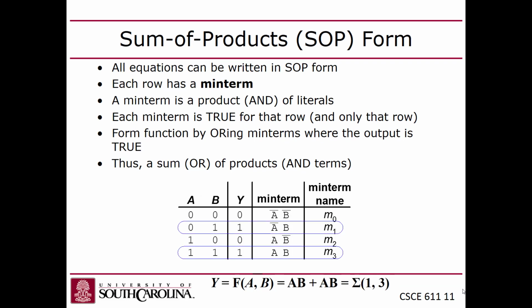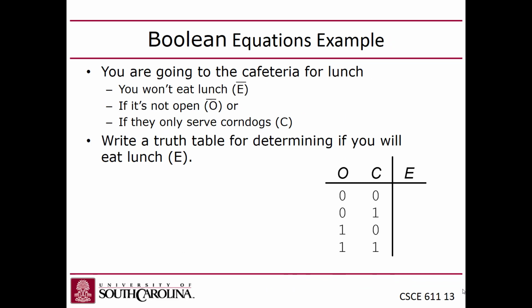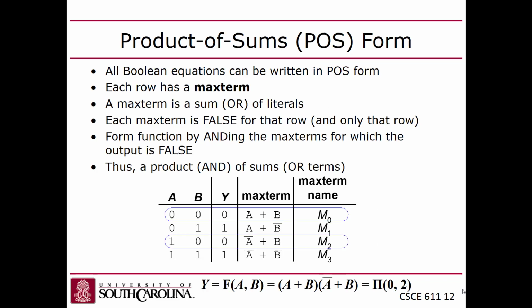I don't have a bigger example. But as you might imagine, if you have a bigger table, your min-terms are going to need AND gates that can support the number of variables. So if I have 3 inputs or 4 inputs, I might have to have a 4 input. But what's more problematic is that I'm going to have an OR gate that sums all the min-terms. That's going to have a number of inputs as defined by the number of min-terms, or the number of ones in my output column. You guys with me?